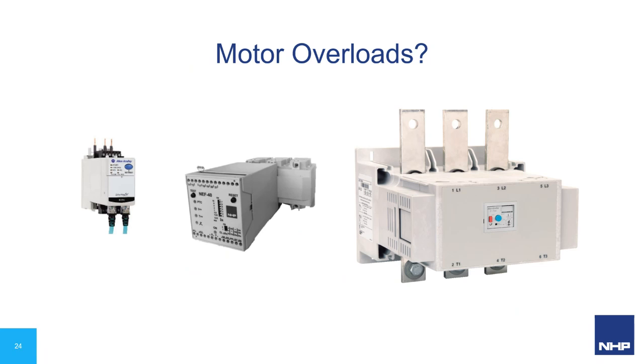The other reason is if we need to comply with Type 2 coordination. With thermal overloads, the answer may be yes, but consult the relevant coordination tables to confirm the need to conform to Type 2. In many cases, electronic overloads do not need to be upgraded unless the frame size of the contactor that we've chosen doesn't allow the overload to be direct mounted, or it's not a surface mountable type.